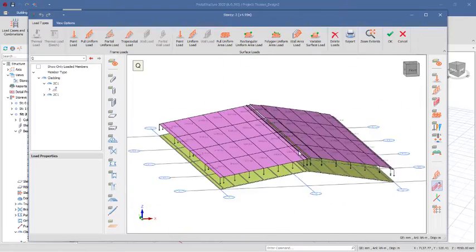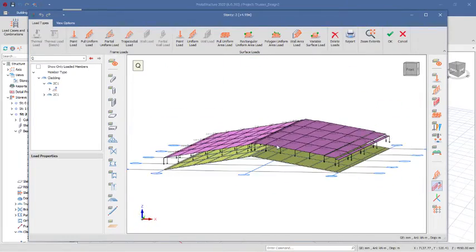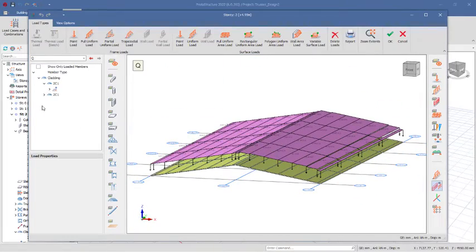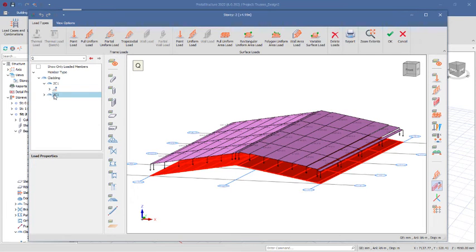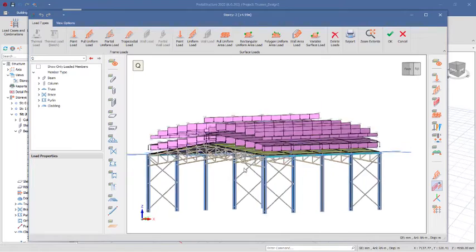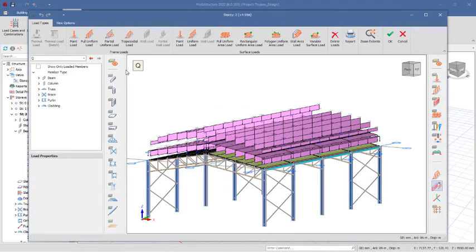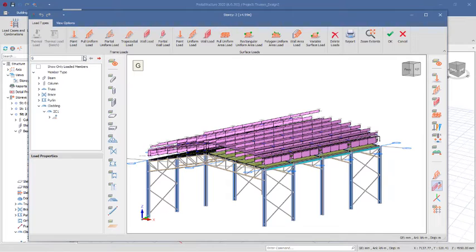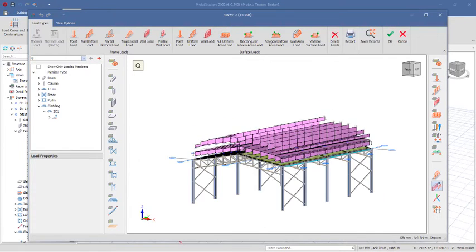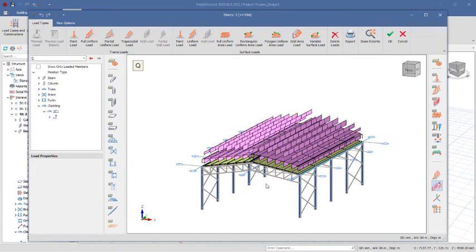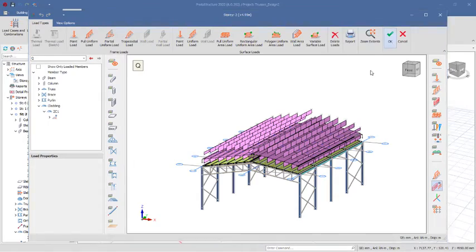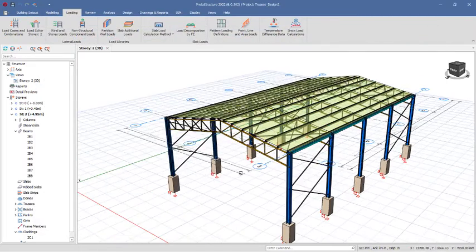successfully, just like this. Okay, so after which you can now select this cladding, right click and clear filter. So once you clear filter, you can see all the loads. Okay, this one is the P load, so you can navigate between the loads. So this is the G load. Alright, this one is the Q load. Alright, so the structure is loaded successfully. Click on the OK option right there. So this is loaded now.